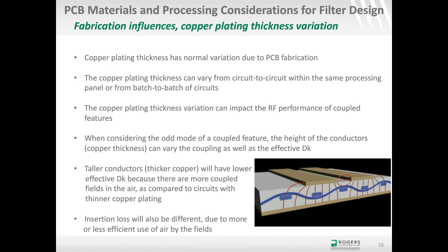In the cases for RF structures that are not coupled, like transmission lines or stubs, the copper plating thickness doesn't make too much difference. It does make a little difference in RF performance, but not a lot. But anything with coupled features, that's where the copper plating thickness can make a pretty big difference. Depending on the design, it can be pretty significant, and in other cases, maybe not. But being that a lot of filter designs are using coupled features, I wanted to talk about the variation of